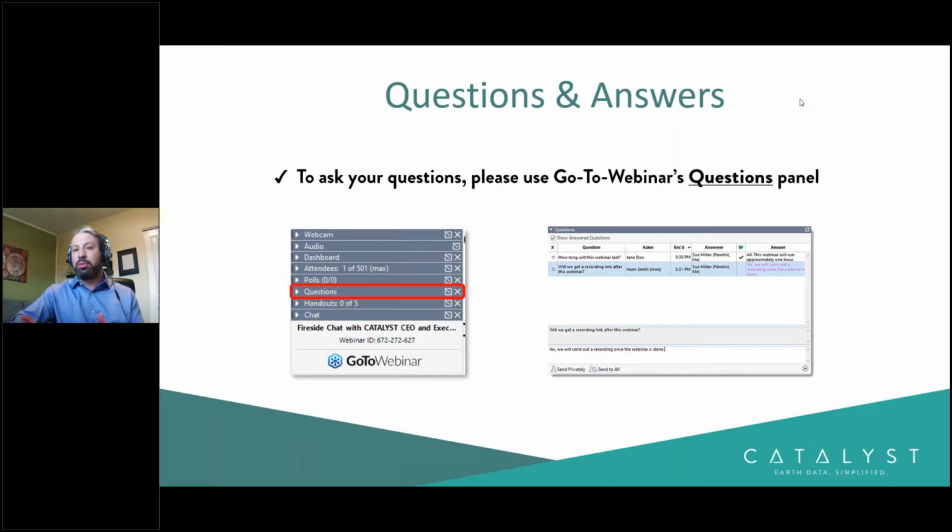So even control points between ortho images might have different accuracy requirements. SuperRegistration, because of its automation, is really a post-ortho process, so it's run on already ortho-rectified imagery in order to make sure that all of your imagery has a really nice, tight alignment.